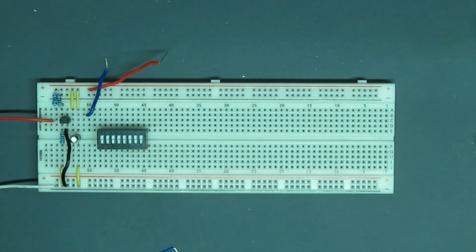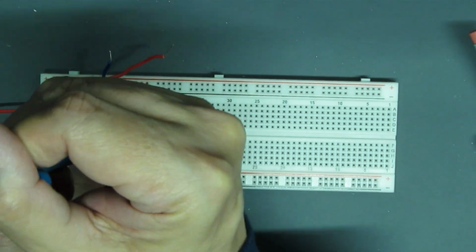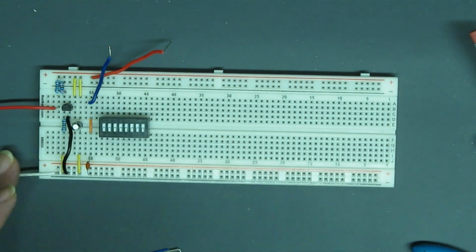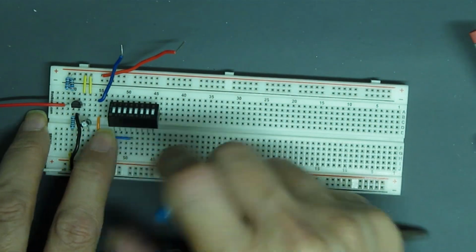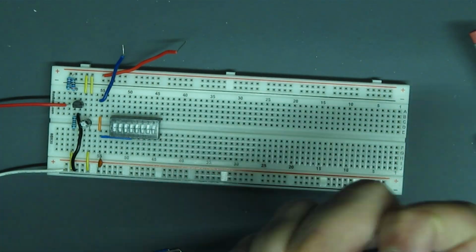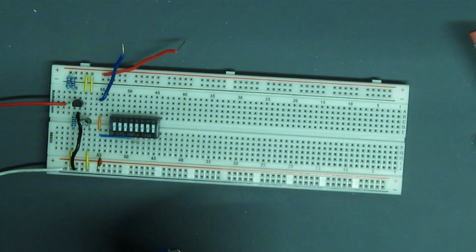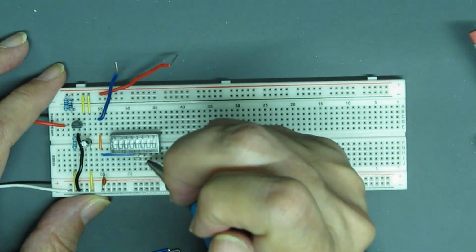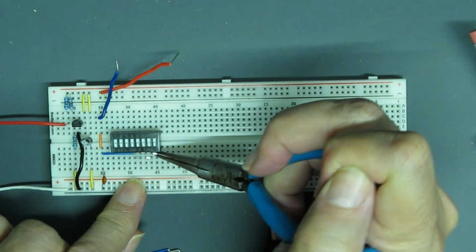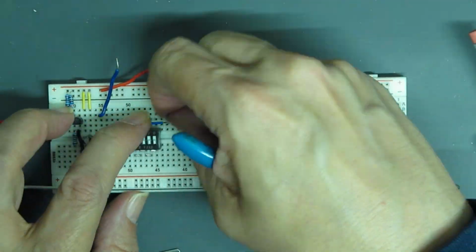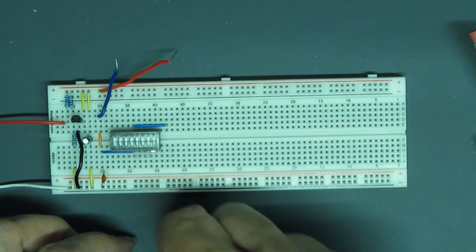I'll lay the bank of dip switches here to sort of plan the layout. I'll put in the 0.1 microfarad bypass cap and run the 7.5 volts to the bottom side of the switches, including a bunch of short jumpers so that the 5 rightmost switches are all connected. And I'll place wires out to the right that will be going to the LEDs.